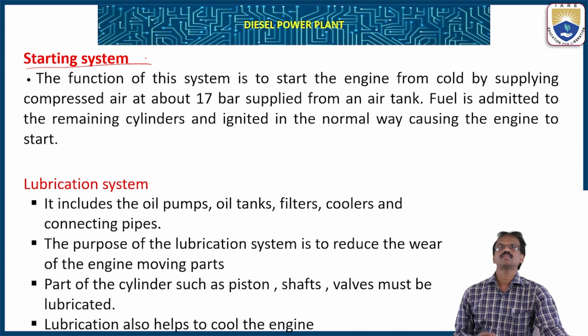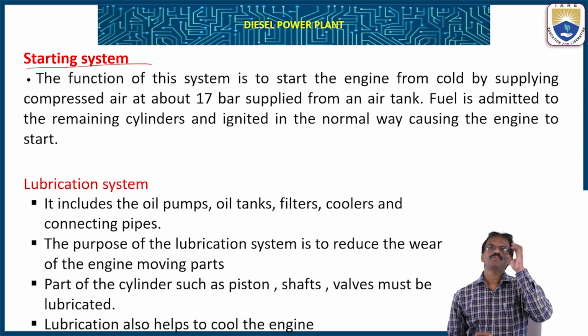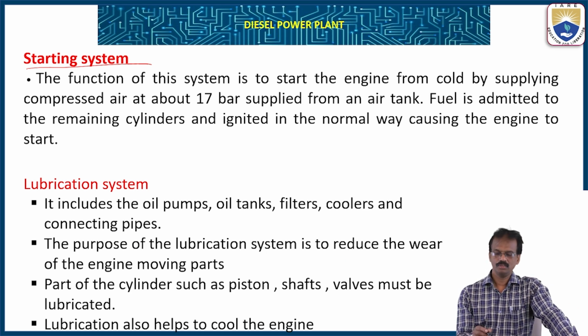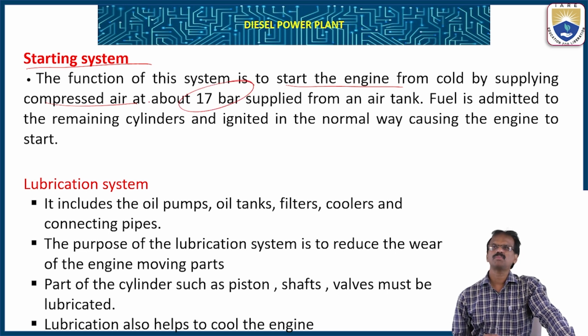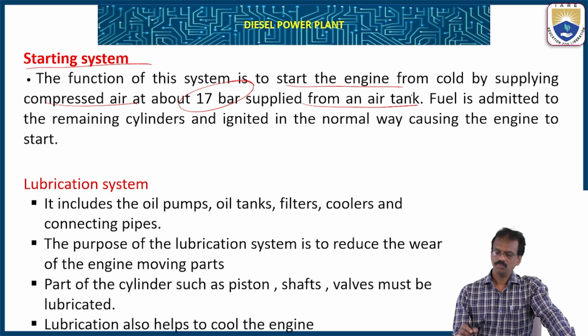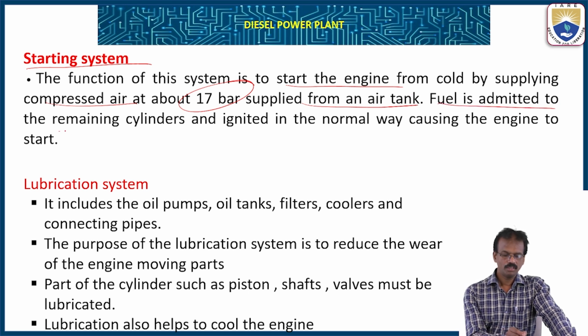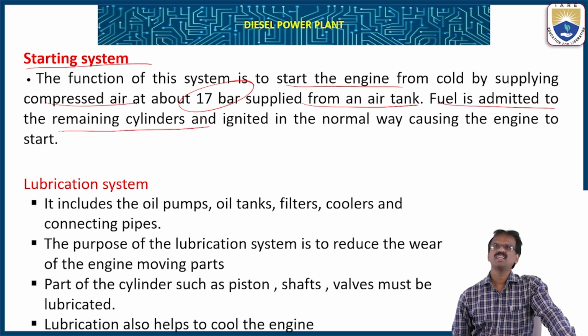The function of this system is to start the engine from cold by supplying compressed air at 17 bar supplied from the air tank, and the fuel is admitted to the remaining cylinders and ignited in the normal way, causing the engine to start.